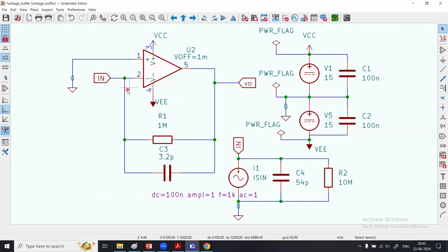What you can do is I use 100 nanoamp input current. I use a resistance of 1 mega, and the input current is applied here, and the output voltage, in fact, is current multiplied by the resistance. So 100 nanoamp multiplied by 1 mega should be around 100 millivolt at the DC analysis, right? 1 mega multiplied by 100 nano.